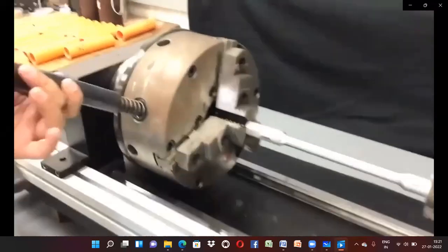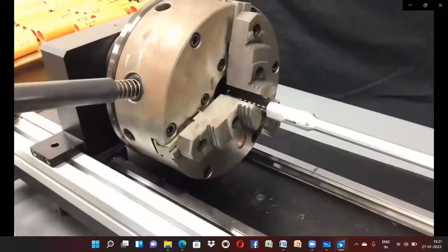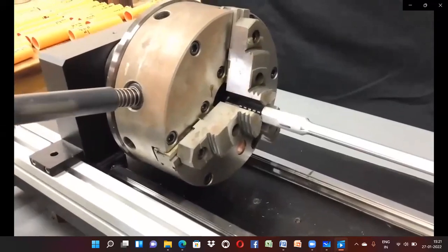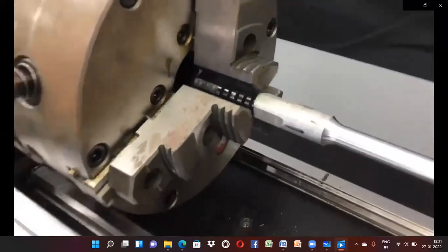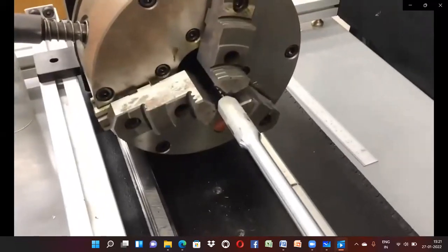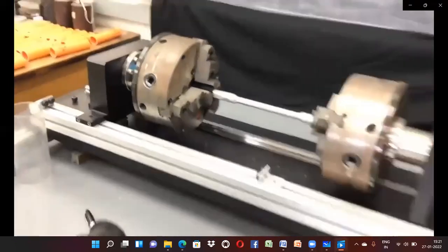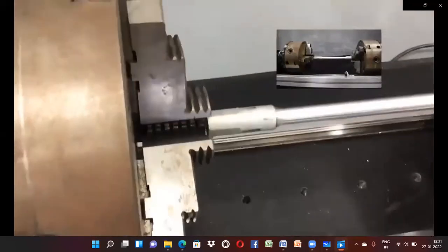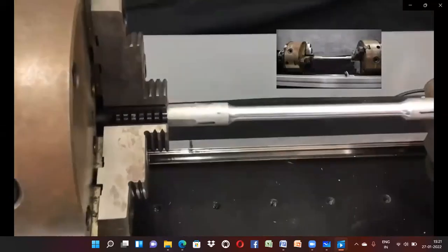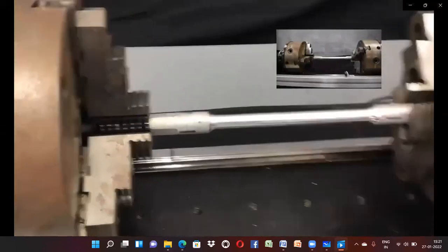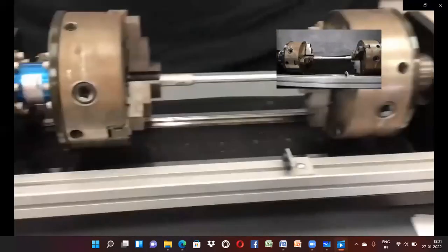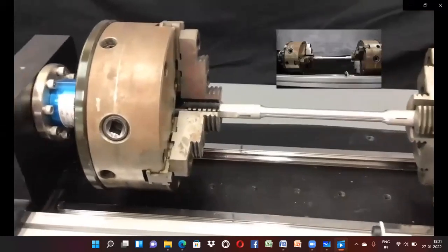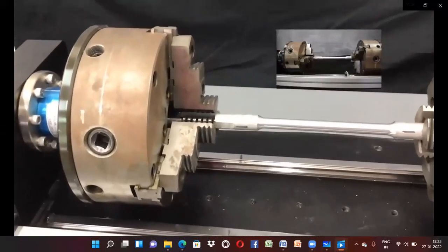So now remember that this is free to slide. And so he's got to open that side. We'll talk a little bit about why it needs to be free to slide. You can see maybe by dumb luck he came pretty close to having the flats and the jaws aligned. Maybe not quite, so it looks like he'll have to jog the torsion side, the motor side, that one right there. So he'll turn the right side so that the flats on the left side align with the jaws on the left side.